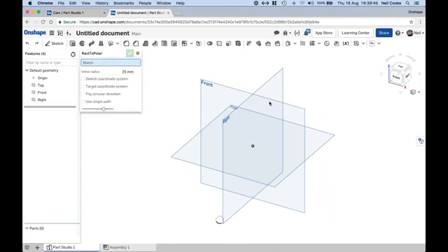Okay. Now, of course, it being a custom feature, it is at the whim of the person who wrote it how it should be used or how easy it is to use. Now, this is pretty straightforward. It's essentially asking for a sketch, which is going to be essentially a graph positioning the position of the follower. Then there's a couple of options here to position it elsewhere. I won't bother with those. Change the direction of the cam, and turn what is really a number of lines and arcs into a spline, which makes more sense as well.